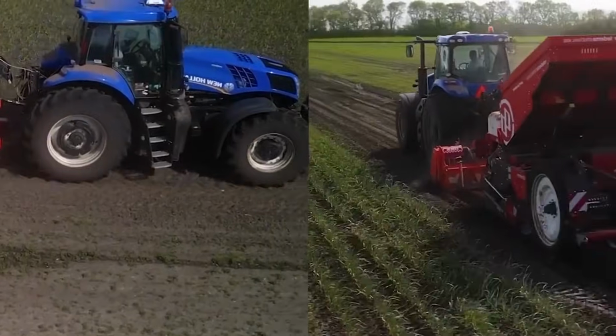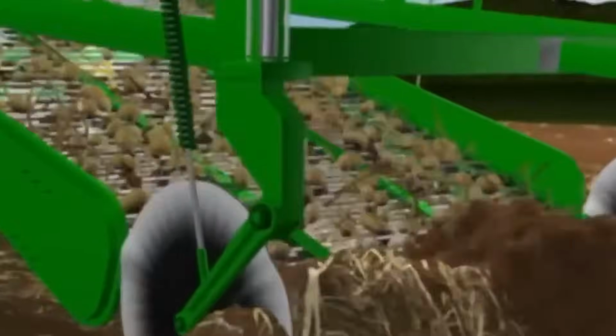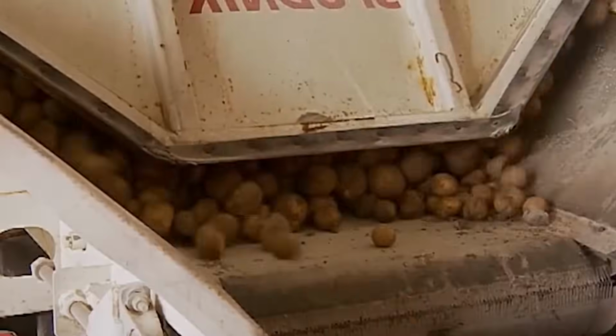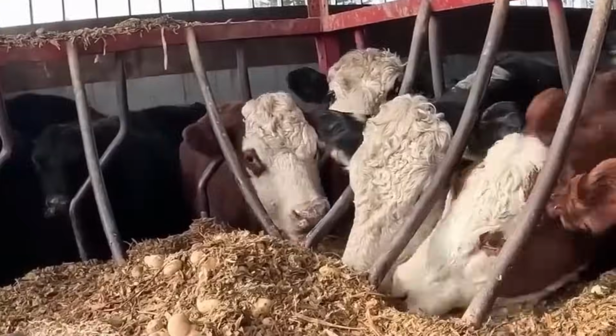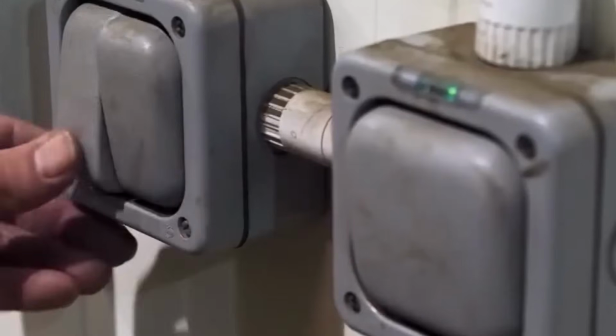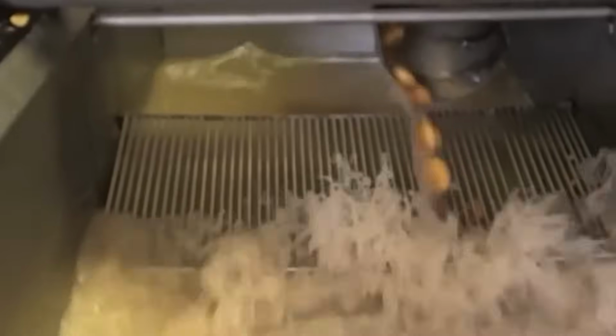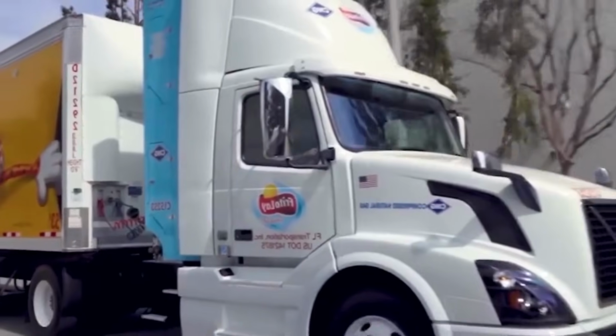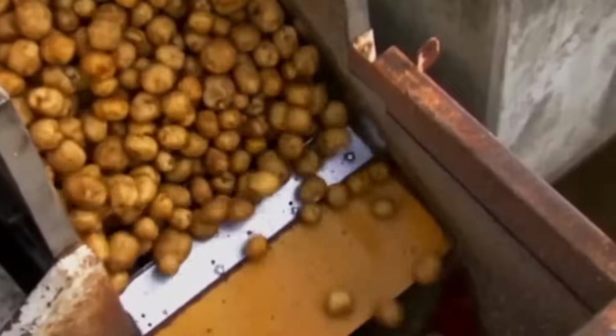Recipes are stored digitally and selected at line start to automatically load all relevant parameters across slicing, frying, seasoning, and packaging modules. Cleaning between flavor changeovers involves flushing slicing and seasoning systems, draining and filtering oil as needed, and changing packaging film rolls, which are flavor specific. Residue is minimized through modular drum systems that can be swapped out quickly and cleaned offline. Line efficiency and waste percentages are recorded for each run and reviewed during shift changeover meetings for continuous improvement.